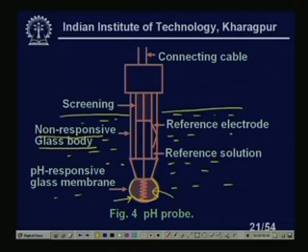And here you see the reference electrode is put in reference solution. This unit is totally separate and closed, so only the electrode leads are coming out. You see the lines going out, and similarly this line, the reference electrode line, is going out. This is a combined electrode, which is what people are mostly using now.